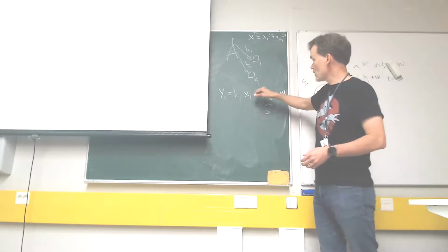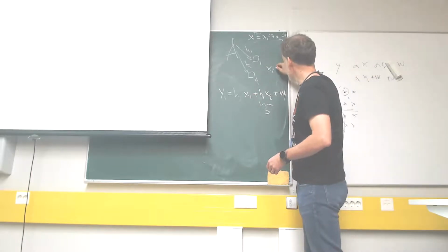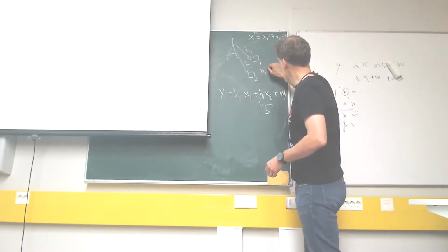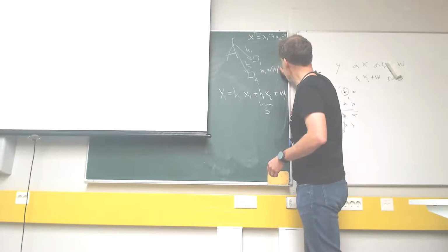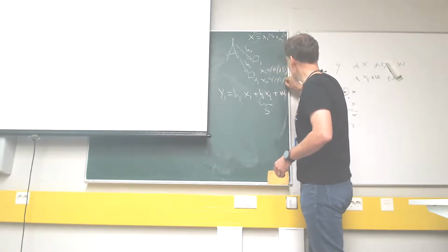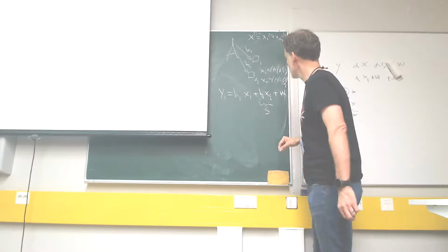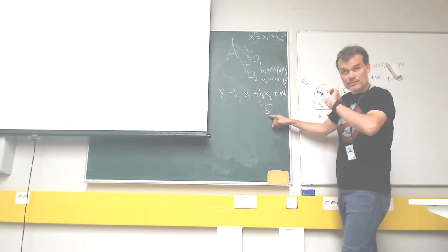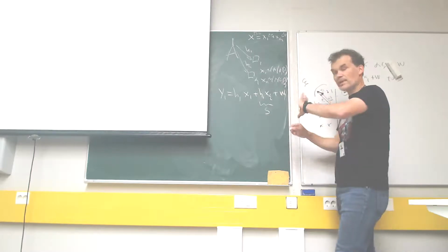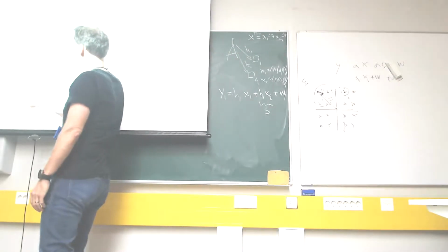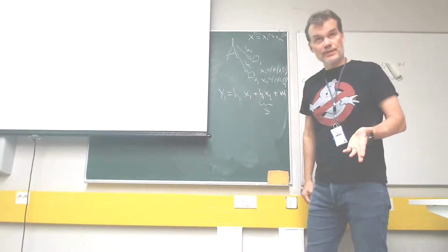And given the power allocation, X1 follows complex Gaussian, zero mean, variance P1, and X2 complex Gaussian, zero mean, variance P2. So given that we can remove this S or pre-subtract it by using this extended constellation idea, the rate of user 1 can be expressed as if user 2 is not there, right?